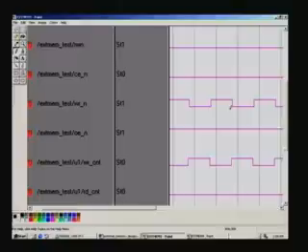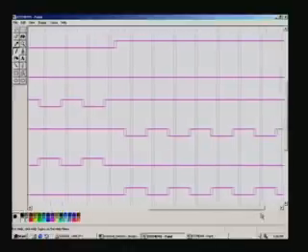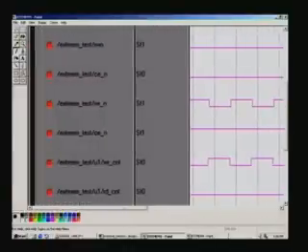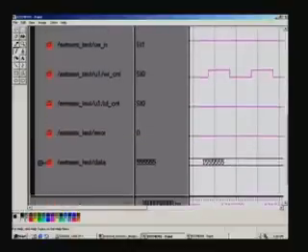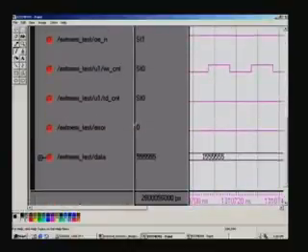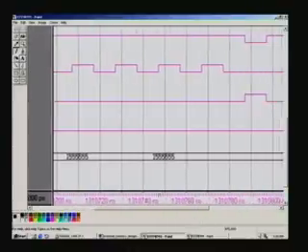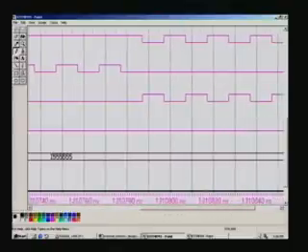Write signals are activated here, and OE is deactivated because there should be no read pulse, and write counter is activated and there is no read counter there, and that is what you see all through. And finally, you have seen error being 0 here, all through it is 0, and this is what we have applied data, and it was changing because write pulse was active, and there is no change during read phase.